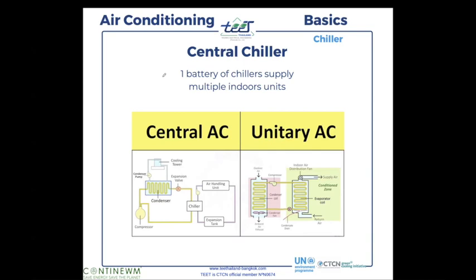If the system breaks, the entire building doesn't have air conditioning. So that's why they have multiple chillers. And depending on the cooling capacity that they need for the entire building, they need several chillers as well. In general, it's never two, it's always three, one spare and two functioning, or 3 or 5 or 7, okay?